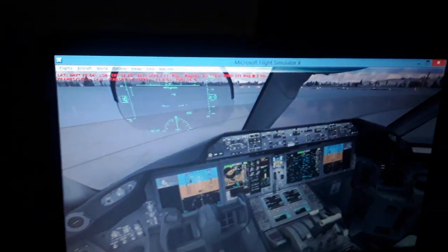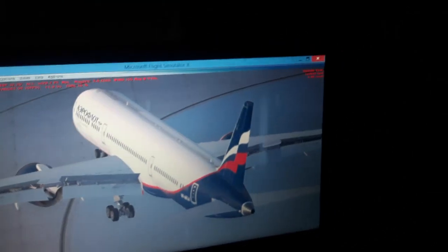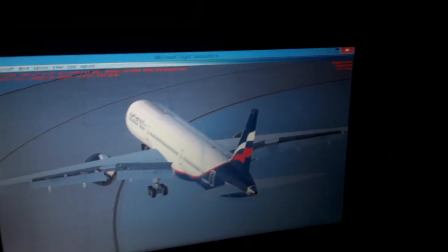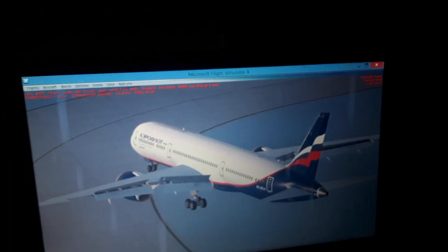So the flight management computer will calculate also the loads from the passengers and the cargo compartments automatically. It will give us the center of gravity of the aircraft for takeoff, climb, cruise, and approach and landing. As we fly, the aircraft will be burning fuel, so the center of gravity in flight is recalculated automatically. Also, this affects the horizontal tail trim stabilizer that I showed you. This trim switch here that you use to trim the horizontal tail of the aircraft up and down, or adjust the elevator in this aircraft.